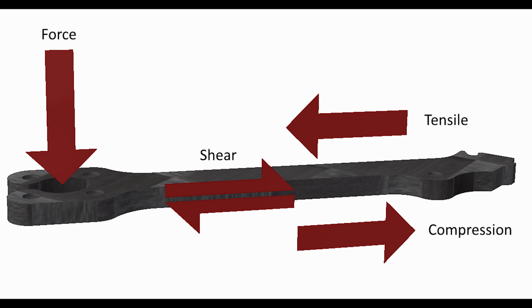Cool. So then the failure point is really the compression of the fibers, and so going with the stronger fibers technically is not giving you a whole lot more strength, because both fibers are weak at compression. In theory, if everything works, yes.